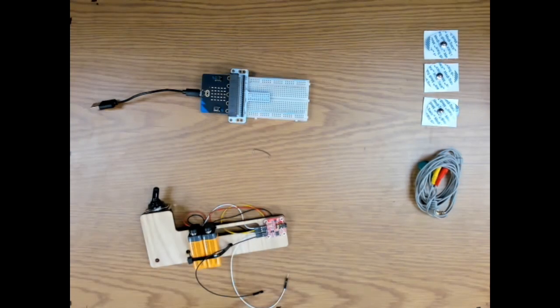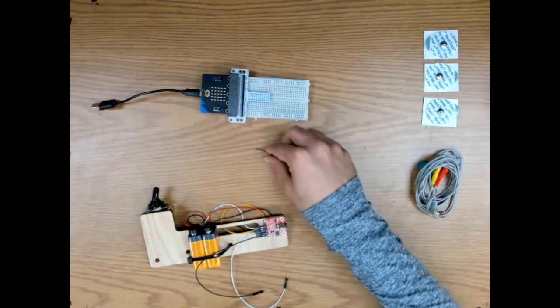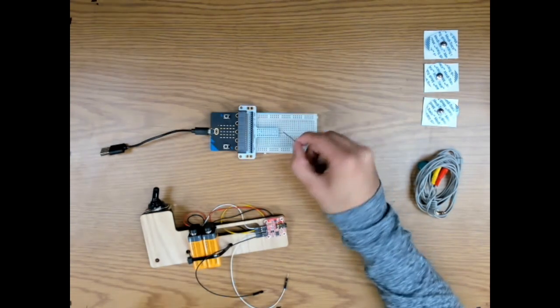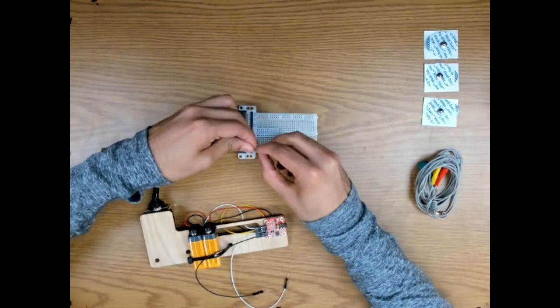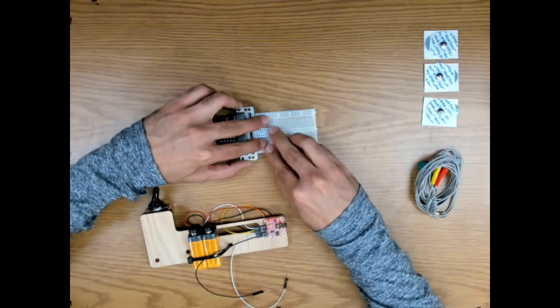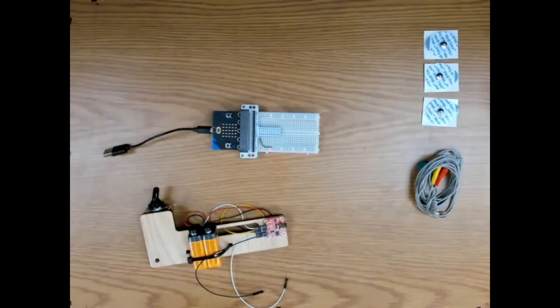It is convenient to put a wire connecting the breadboard ground to the microbit ground in the breakout board. Usually the ground is denoted by the blue line that runs across the breadboard. This will be useful in the future to connect all the ground connections into the breadboard with more space.